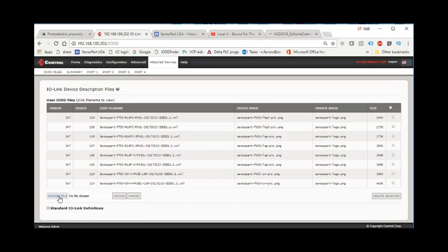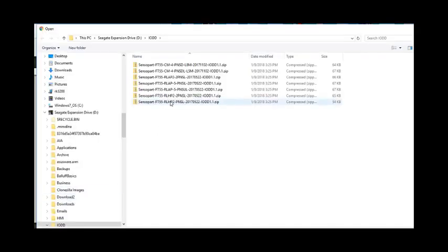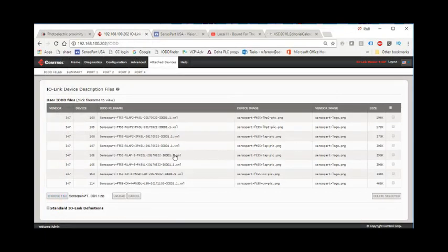From the dialog box, we want to pick the CM with a 5-pin connector. And then click the Upload button. Notice that was in a zip format. The zip file includes the XML text file and a picture and icon of the sensor. Now we go to Config,